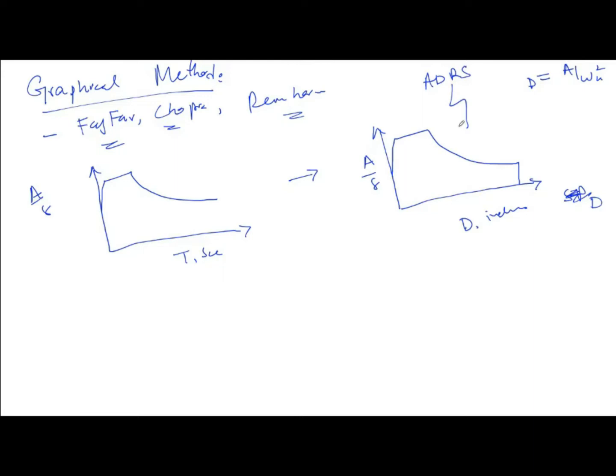The peak deformation of the system is determined in the next step. The peak deformation is obtained since we know the ductility of the system, we know the vibration period of the system, and we know the yield displacement of the system. We can obtain how much maximum displacement demand will be acting on the system. The resulting data pairs A_y and D are plotted to obtain the demand diagram for the inelastic system. So this ADRS is also known as the demand diagram.